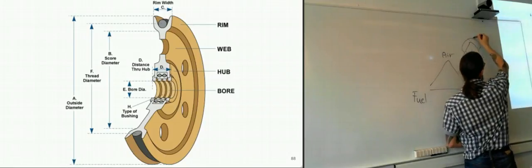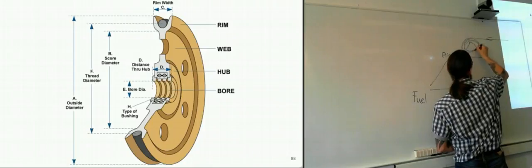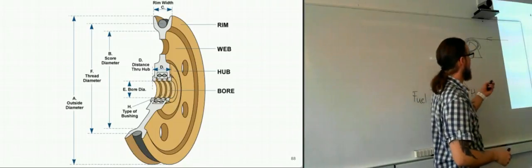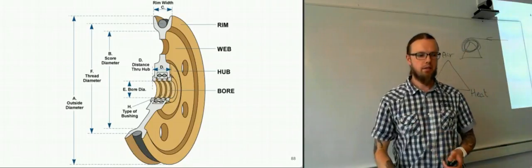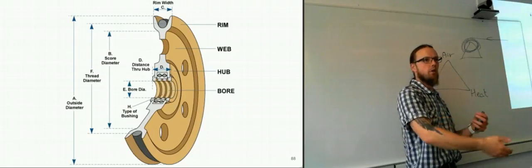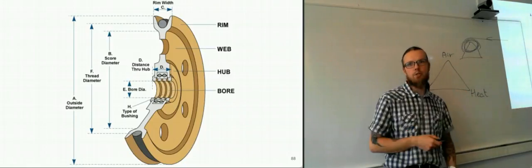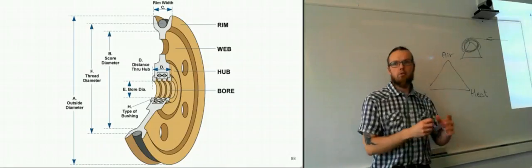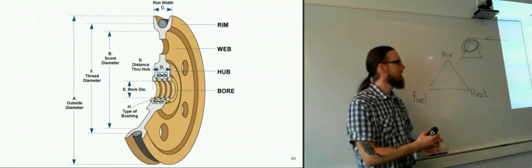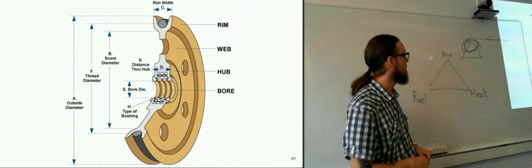In the winch itself, it will be pulling on this wire, and then we'll be gathering up the steel wire inside the drum. And if the steel wire is being heated up by friction on its way in, then the heat is going to be trapped there, because it's coming layer upon layer upon layer of wire on top of here, and everything is heated up. So you're creating a dangerous situation there, because these lifting wires are usually coated with grease also, and grease is flammable. So it's not a good situation to have very hot wires coated with grease and everything.